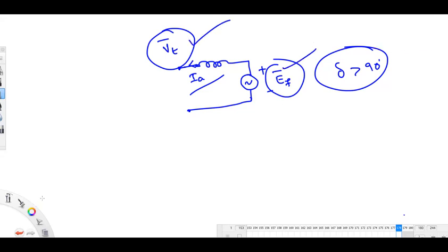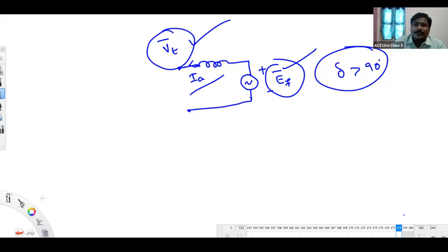That will decide the system stability. Don't go for complexity directly. You take this current in the same direction of the motor, into the motor, and you take that itself as your reference if you want, and you show VT bar and EF bar by using KVL.